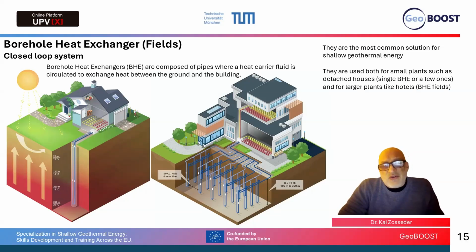And then, of course, you have borehole heat exchanger fields, and you need a spacing between these specific borehole heat exchangers, because some borehole heat exchanger is using the heat from the underground and it's cooling down in the heating season, and then it should not be influenced.